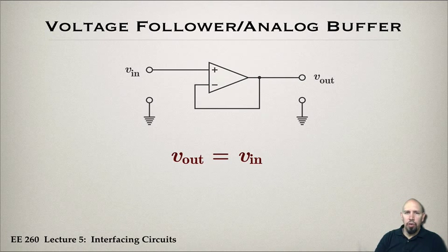When you get into later classes on systems, we will look at why feedback is used. In this case, it's actually necessary to use feedback because remember, if you just apply a voltage across the terminals of the operational amplifier, you'll get the rails. Here, you won't get the rails; the output voltage will be equal to the input voltage. So if the output voltage is equal to the input voltage, why do we need a circuit? Why don't we just use the input voltage?